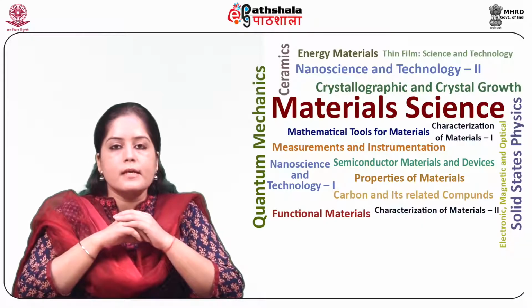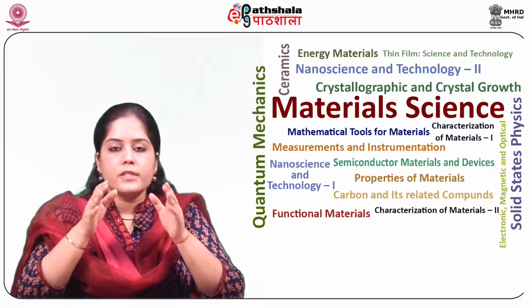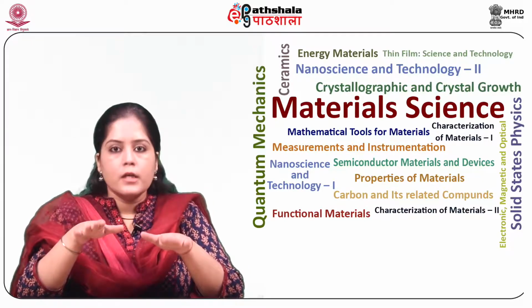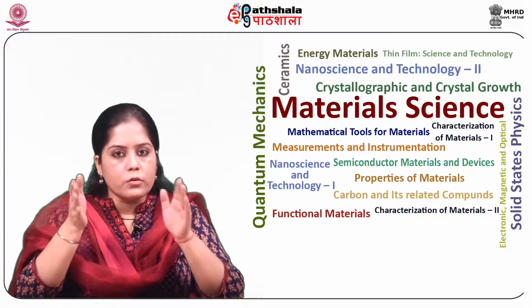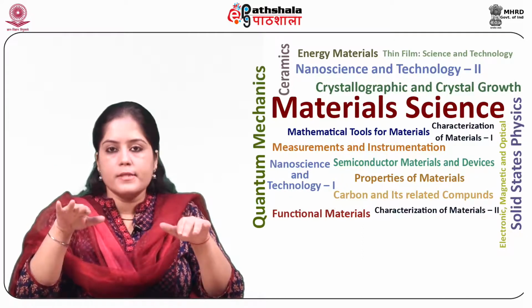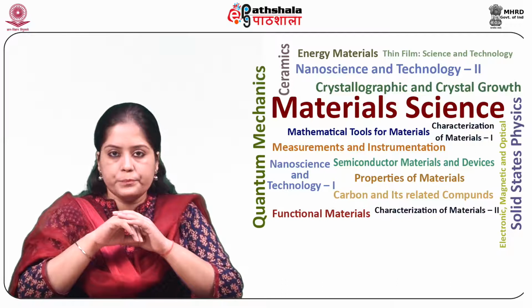So students, let us start with a basic introduction about the module. A transferred electron device is a moderate power device which has low oscillator phase noise, and it is a form of diode used at all microwave frequencies from 300 MHz to 300 GHz.